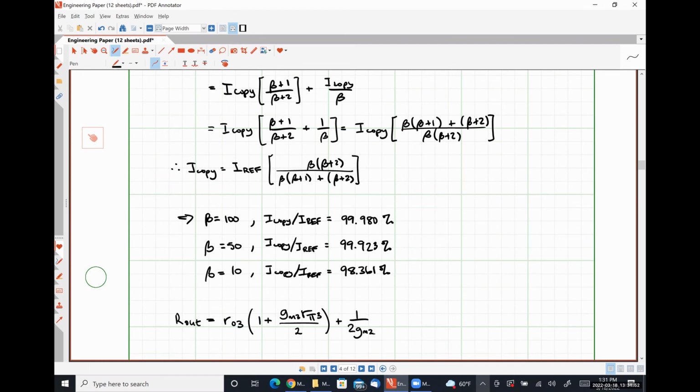So we do still absolutely get an increase in the output resistance, but it's not as large as we would have seen from the Cascode. So that's the trade-off there. Practically speaking, you're either going to wind up using a Cascode or a Wilson, and it depends on whether you value output resistance higher than its ability to directly copy the reference current. So whichever one you need more is the mirror that you should use. All right, that's enough out of me for today.